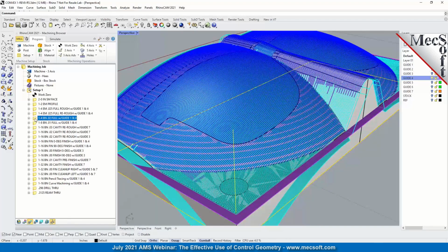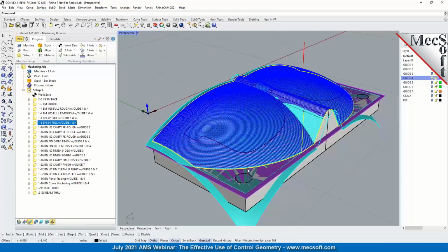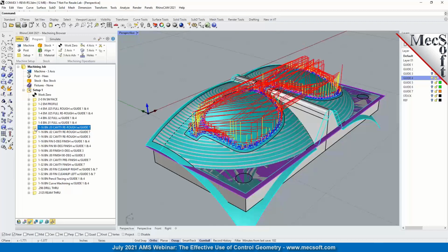And here's another pre-finishing operation on this same area, but in this case it's contained to this edge of the cavity or the insert block parting surface. Okay, so this is the parting plane, this is the actual parting surface. So let's go on further.